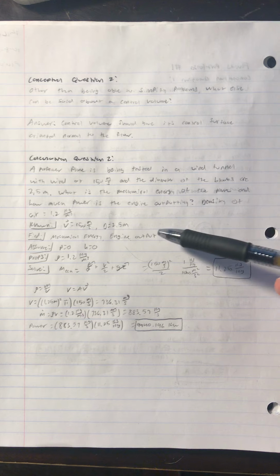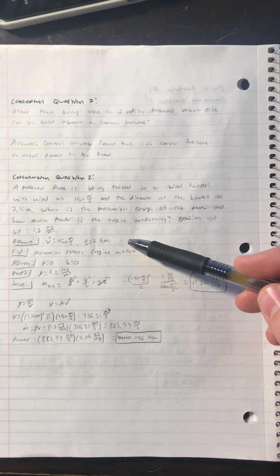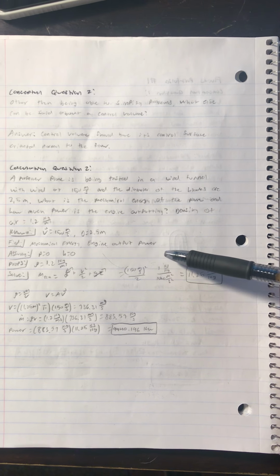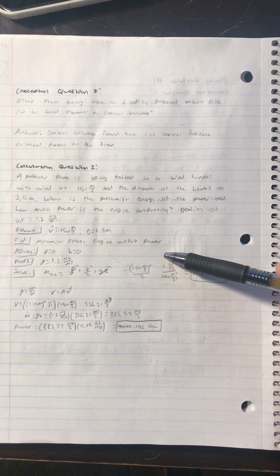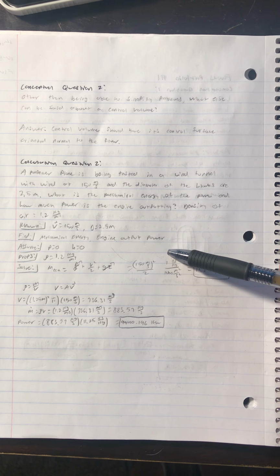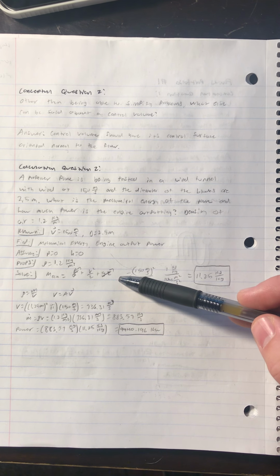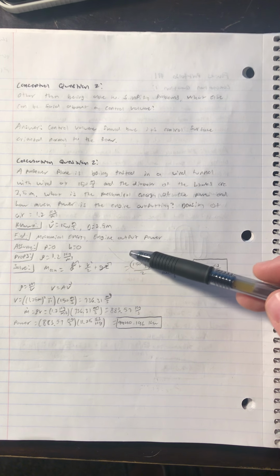So we go to our knowns, which we write down: 150 meters per second and 2.5 meters for a diameter. We're trying to find mechanical energy and an engine output power. We are assuming a pressure of 0 and a height of 0. So in order to simplify, we use a simplified Bernoulli's, and then our property is 1.2 kilograms per meter cubed.